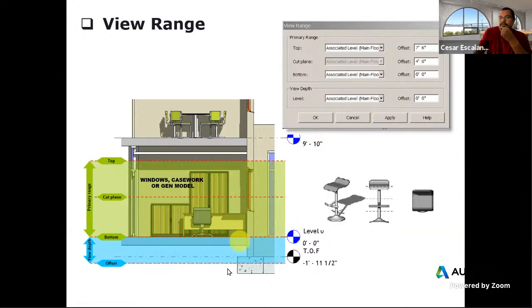There are also special line types associated with certain categories. For example, if a structural element or a structural wall falls in the view depth, those elements are going to be displayed in a floor plan as projection line, dash line. I don't see architects using much of that.